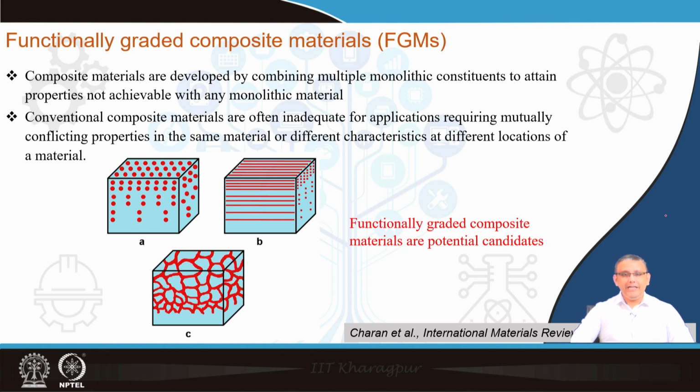As we learned already, composite materials are inherently heterogeneous materials. That means, if we look at a very small length scale, there is always a distribution difference between different regions. But generally the composite materials are macroscopically homogeneous. That means, although at a quite small length scale there are distribution differences, if the length scale of the measurement is much bigger than the microscopic length scale, then the composites are globally or macroscopically homogeneous.